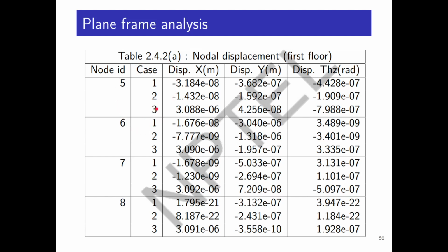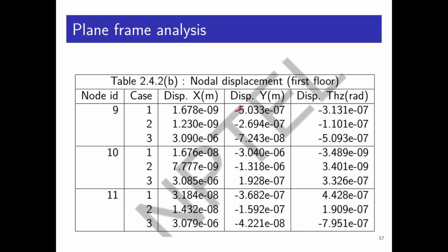That is because of, I forgot the term, you have to see the mode shape. There's a term called mode participation factor. You have to find all those modes whose participation factors sum to more than 90% contribution, and only those mode shapes are considered. Basically the first two or three contribute more than 90% of the mode participation factor, so that's why they have taken the first three only. For more understanding, you can opt for the earthquake analysis and finite element analysis courses.